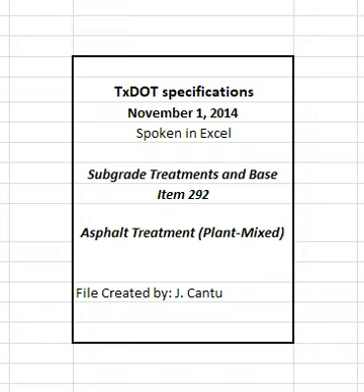Reimburse the department for subsequent mixture designs or partial designs necessitated by changes in the material or requests by the contractor. The engineer may accept a design from the contractor that is performed in accordance with TEX 126E and is submitted on the department-provided template. Obtain mixture design verification and approval before beginning production.